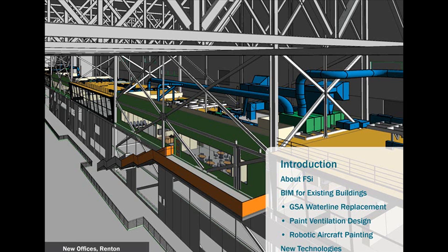Oh yeah, on this project. One thing that was really useful about employing Revit here is that we're putting our VAV boxes and our mechanical equipment right on the walkable ceiling above the fourth floor. The guys who are going to be maintaining those VAV boxes, hauling in new filters, and replacing whatever happens to break down the line need to be able to roll a cart around that fifth floor deck level and get to every single VAV box. So we showed that we could roll a cart to each one of them without getting in the way of, or rolling over, a piece of pipe or a piece of duct.